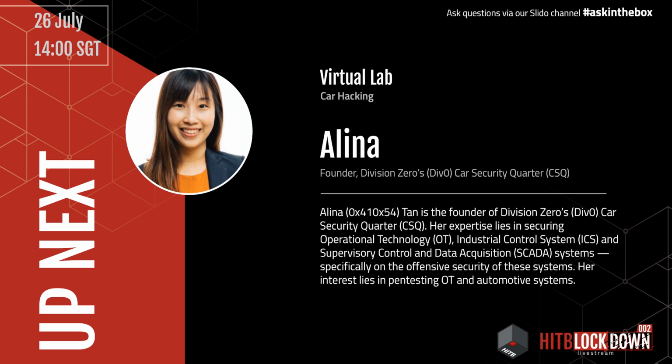So basically, there are actually different protocols within a vehicle. You have your CAN bus, your LIN bus, your FlexRay and so on. They can all work with each other via a central gateway, and the central gateway itself does all the translation. For example, we have a central gateway in our test bench 2 as well, in the CTF, which is also hidden from sight. The central gateway translates the MOST protocol to CAN bus and all other devices that portray on the cluster meter.